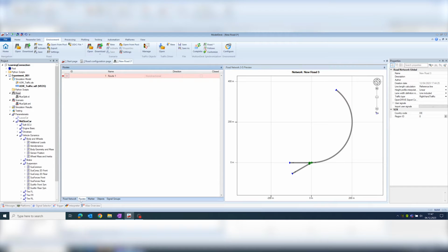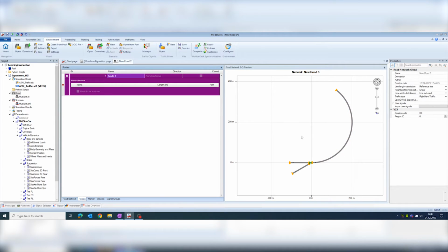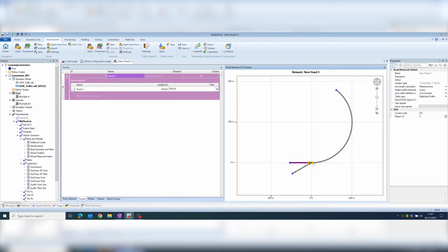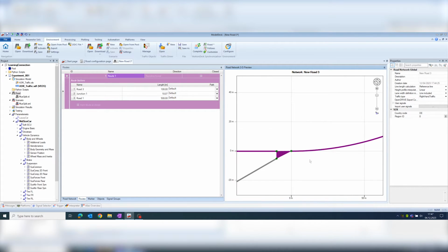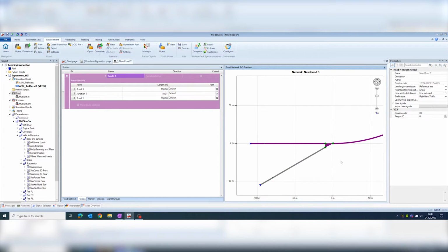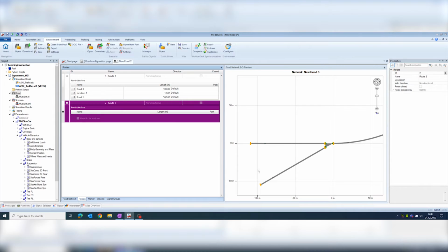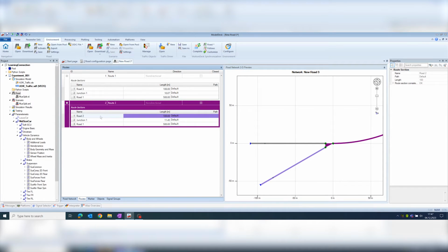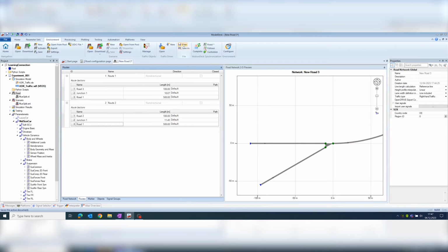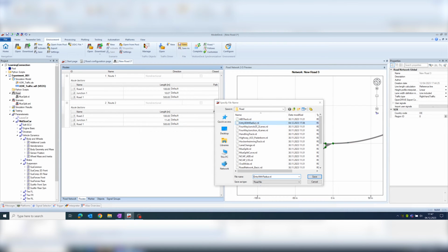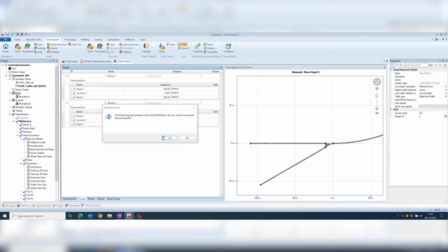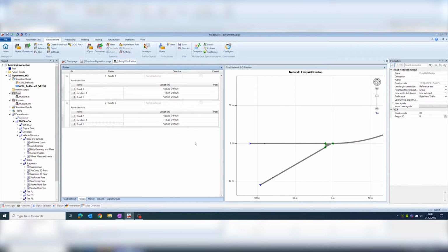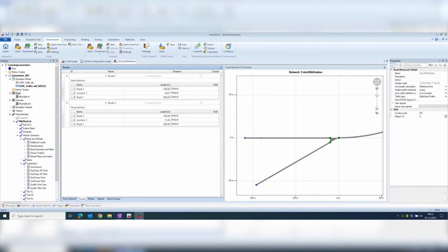After configuring all necessary elements, I now need to provide information on how traffic participants can move through the network. This is done by selecting the connecting points that should be contained in the route. Depending on the number of routes and the complexity of the road network, it might be advisable to define individual names for the routes. As the final step in the road creation, I can now save it as a part